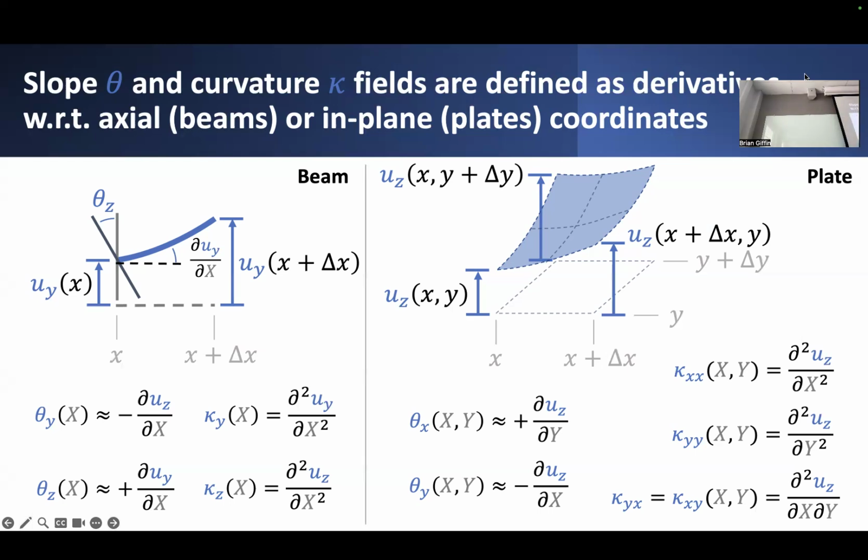Otherwise, in the more general case of Reissner-Mindlin plate theory, obviously, the fiber could deform in any arbitrary fashion, regardless of how the plate is necessarily deforming, and you'd have to treat its relative orientation as an independent unknown. But in the case of Kirchhoff-Love plate theory, as in the case of Euler-Bernoulli beam theory, it all just depends on transverse displacement alone, which is really nice because in the end, all we have to do to combine all these things together is suppose that I can define some intermediate quantities, things that I'll just call curvature.